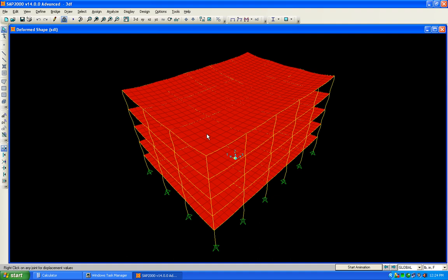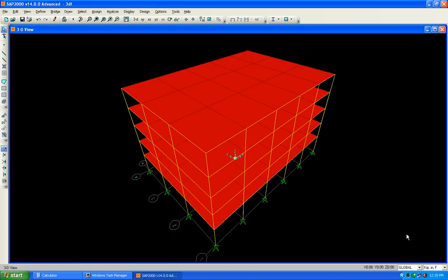For this movement we will keep this area section and allow the deflection of this much, and we'll further move on. ACI requires a serviceability requirement, and for serviceability your deflection should be less than 1 inch. Now, we still have a problem. We are increasing the depth of the slab, but our deflection is not under control. What to do with this?